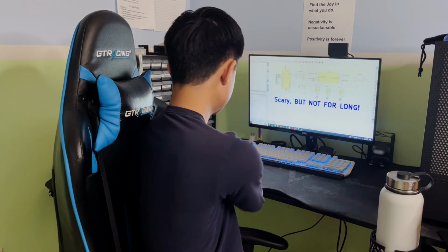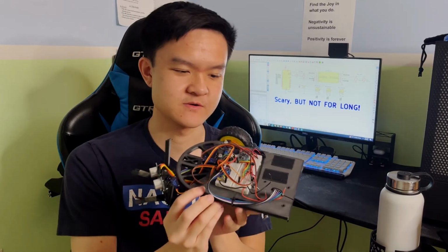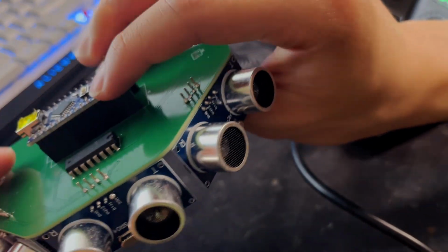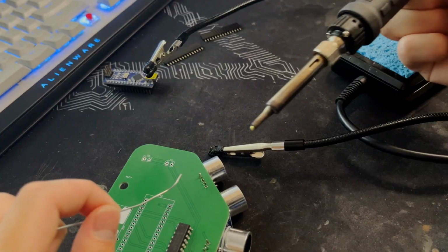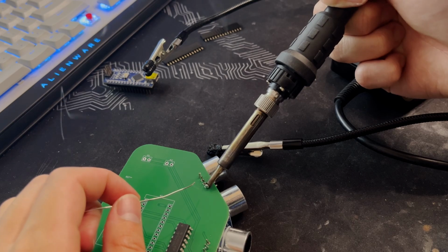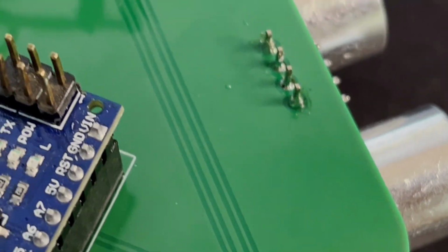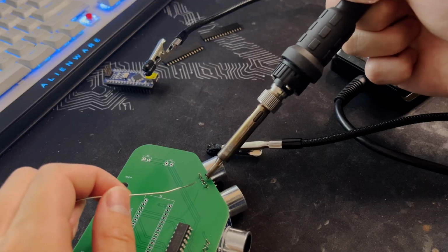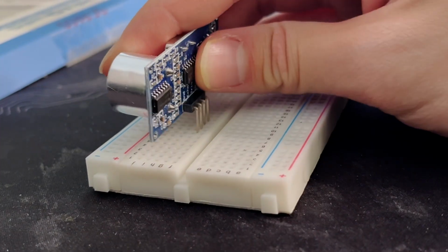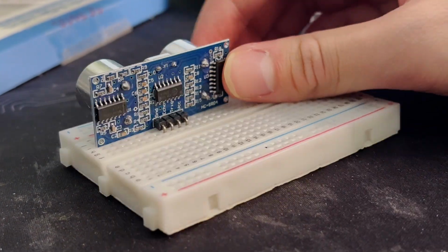Of course, you can make the Tinkercad circuit in real life with a breadboard, but you can imagine if the circuit was bigger, you could see how messy it gets. The solution? Printed circuit boards, PCBs for short. PCBs are essentially boards that can make the same electrical connections between components, but do it more compactly and securely compared to using normal wires. This is because the wires are embedded in the board, and the connections to the board are made through melting metal, which is much more permanent than a friction fit in a breadboard hole, for example.